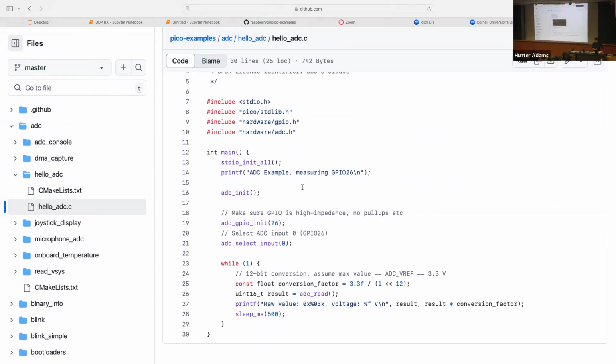That's better. This shows the minimum setup for the ADC that you'll be using in lab this week. All that I want to point out is, when we talked through that ADC demo last time, I showed that there was a bunch of FIFO configuration and DMA configuration and so forth. In your case, for this lab, all that you need to do is call ADC init in main.